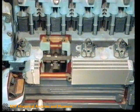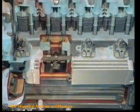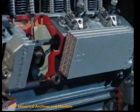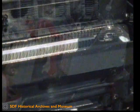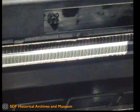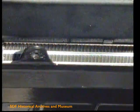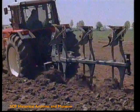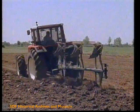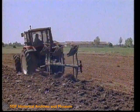The lubricating oil circuit is provided with a cooler. In order to maintain the oil temperature at optimum values, in certain climatic conditions, a thermostat can be fitted to the cooler, which allows the oil to be cooled only when beyond a preset temperature. Reliability of the lubricating system, even during the most demanding uses. Maintenance of the physical chemical properties of the oil for optimum lubrication.